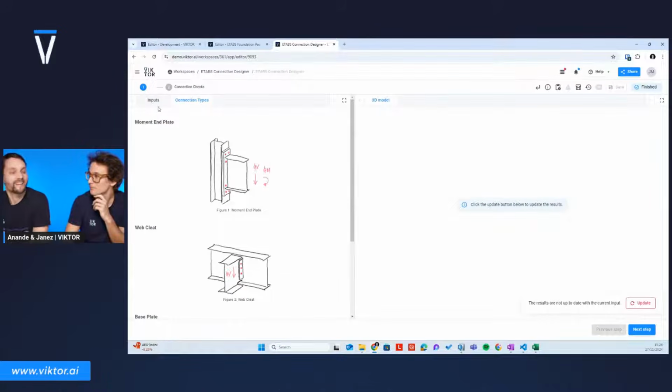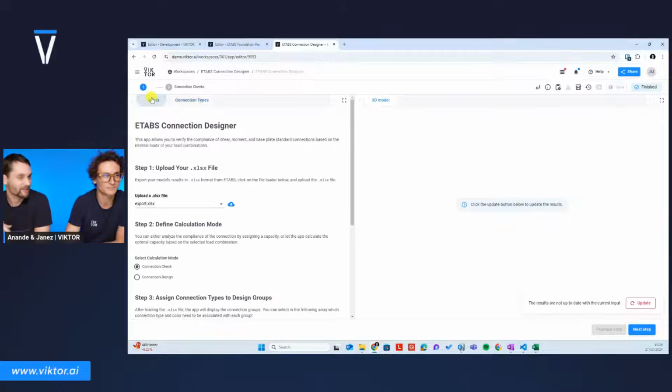Oh, funny, because I've worked a lot in the offshore industry, and they have the same system. They have DNV, which is a certification agency for mostly offshore structures. They have exactly the same method. They have all kinds of standard connections, and depending on the loading and the beam, you can choose a connection. Yeah, correct. You try, of course, to use as much of that standard connection as possible, because then the certification is easier and it's less work. And then only for the custom ones, you do something different. Indeed, it's really valuable to have all these standardizations in place, just because you avoid so many mistakes later on down the track.